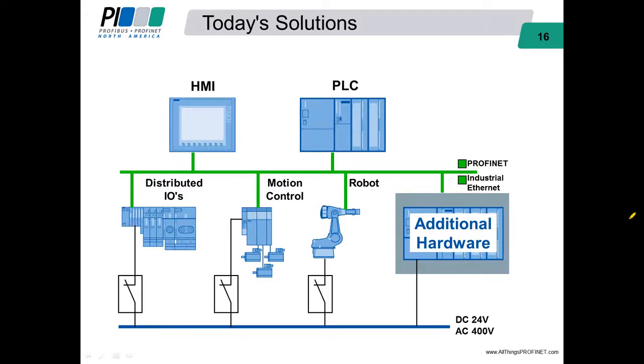If they were trying to do that today without using PROFIenergy, this would be the situation that they would be in. They could add a manual switch ahead of some of the devices that they wanted to control. If these are manual devices requiring a person to go throw them on or off, then they've got to have somebody who throws them on and off in the right order. And they also have to be very careful because it may not be possible to shut all the power off to a particular device. Maybe there are safety circuits that have to remain in operation. Well, instead of using manual devices, they could use an electromechanical contactor, for example, and then they could write some code in the PLC to decide when to turn those on and off. Unfortunately, that turns out to be very expensive custom programming and potentially some very expensive hardware to go with that.